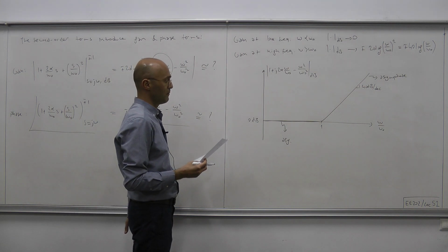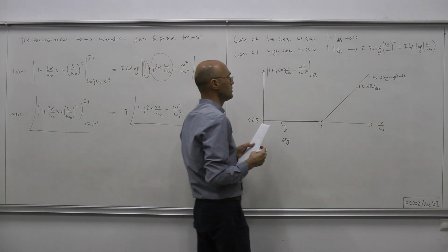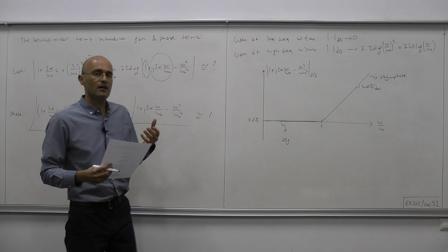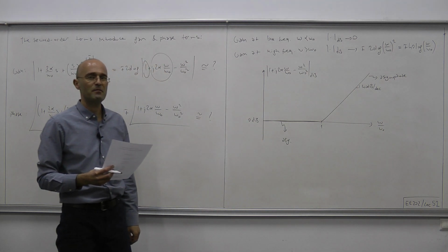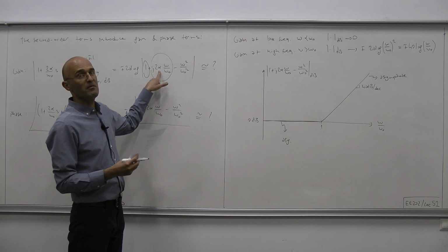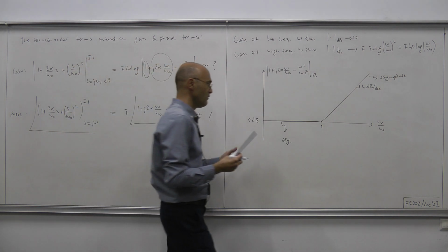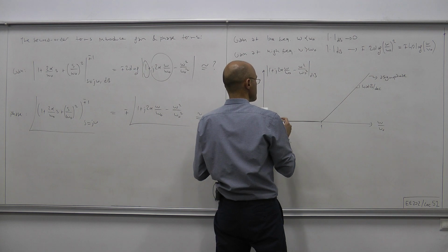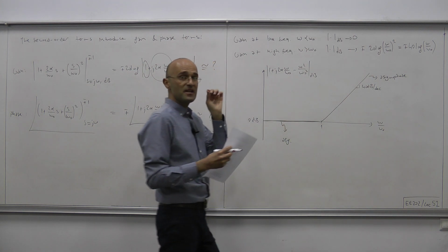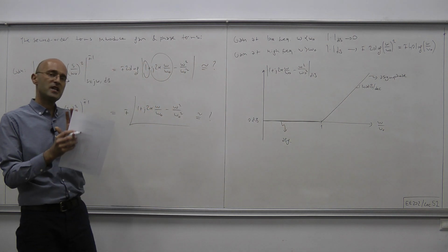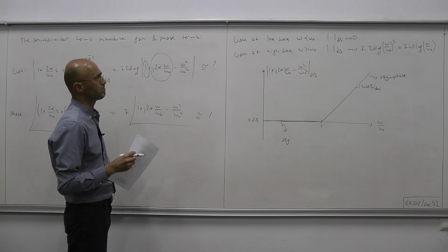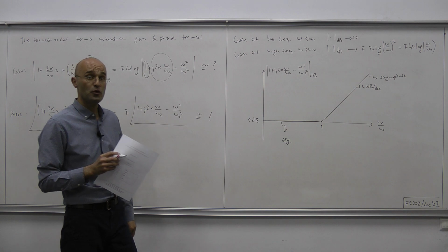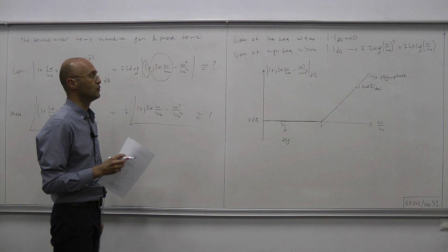Now, how about the actual curve compared to that approximation? How far it is from the asymptotes depends on the damping factor alpha. When alpha equals 1, that's the smallest alpha where we can express the second order term as a product of two first order terms with real roots.